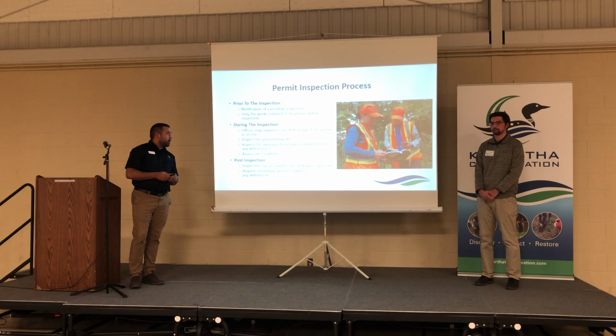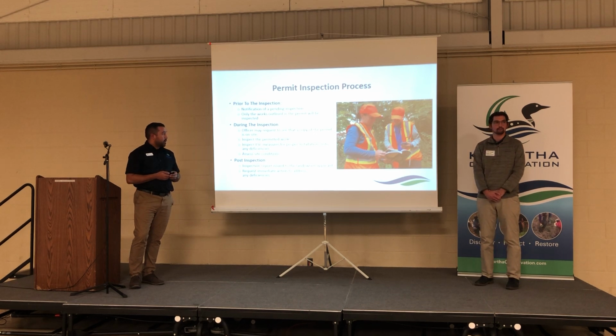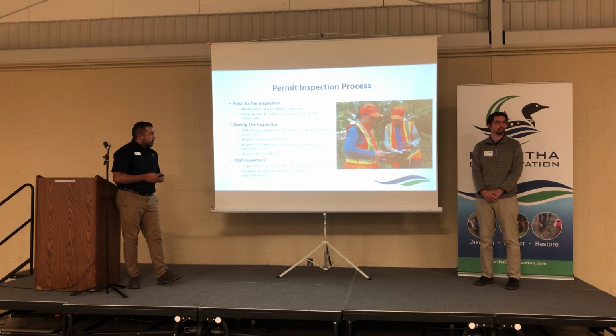During the inspection, the officer may request to see that a copy of the permit is on site and available to anybody working on the site. And they'll also go through the authorized works to see the progress and inspect them in general, and make some notes on whether a follow-up inspection will be required at the end of the project or not. Also to inspect the ESC measures for proper installation, note any deficiencies, and again to assess the site conditions.